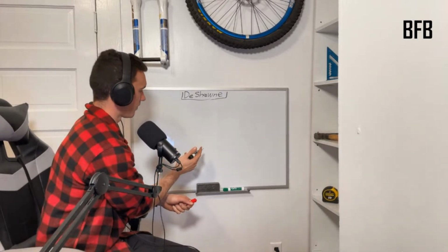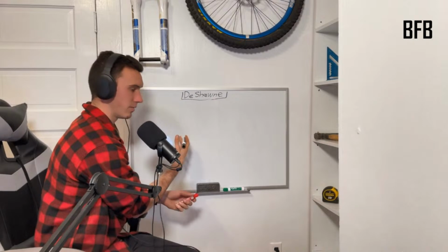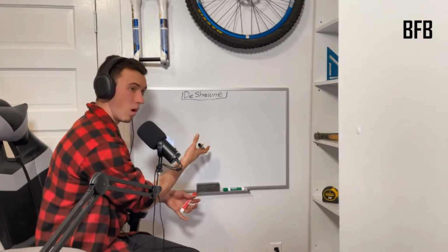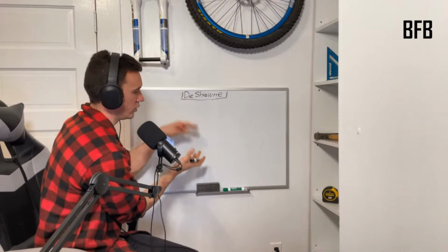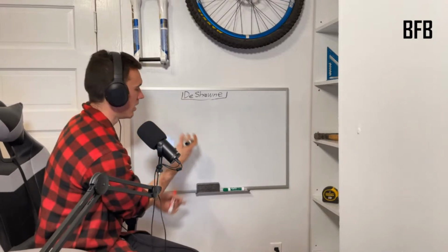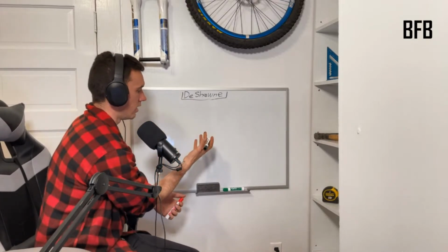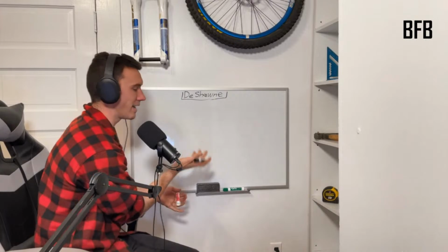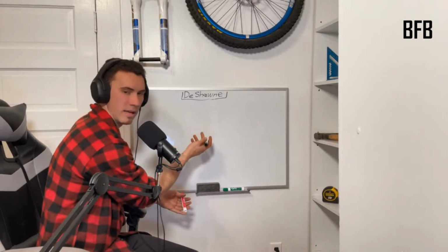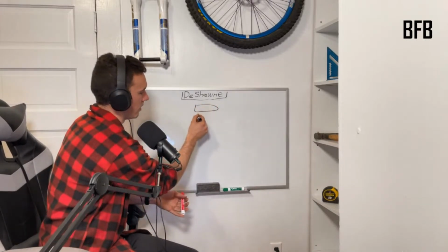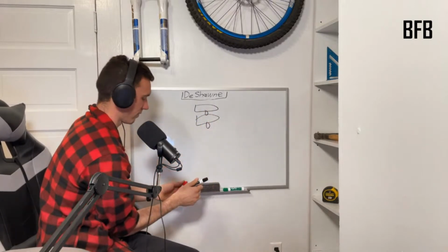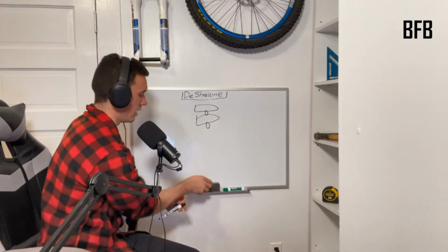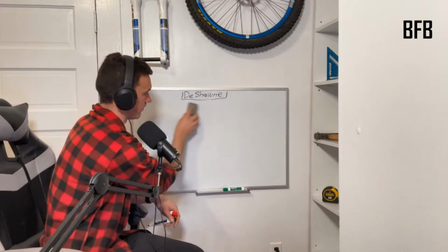Okay. So we talked about wind loading a wall that makes a diaphragm bend. We talked about how the individual effects can add up. Let's talk a little bit about the whole sheathing thing. So I talked before about adding blocks in, right? You got a beam and a beam, you're gonna add a block in the middle. Well, that's more blocks and more wood. What I talked about was sheathing products.